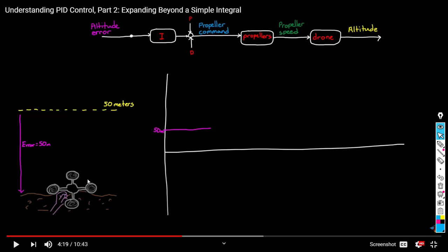Even after saturating, you keep holding it, and you are accumulating error. It starts adding up, increasing the command to the propellers, telling them to spin faster because the system needs more force to take off. The propellers will keep up with the command, spinning.